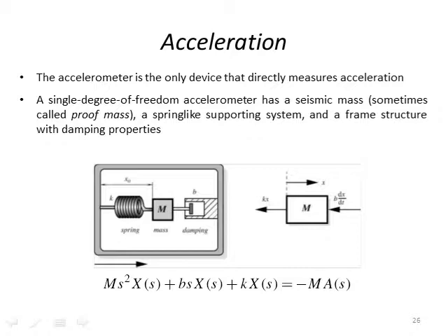And then the Laplace transform of this block diagram is shown on the bottom. You can see that on the right-hand side we have this mass and the different forces on the mass due to the spring constant and a displacement in x, and then our damping coefficient, which is b, and the velocity, so b times v.